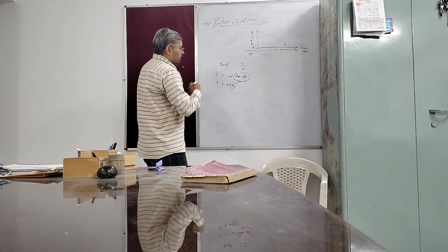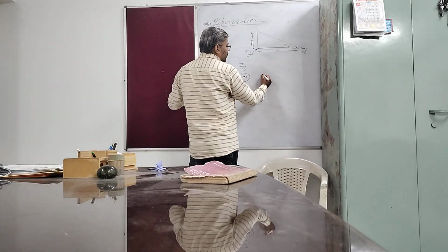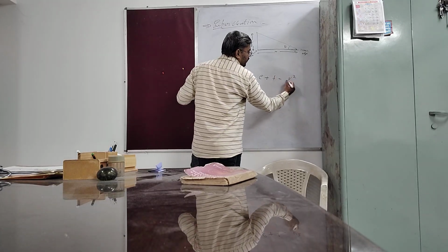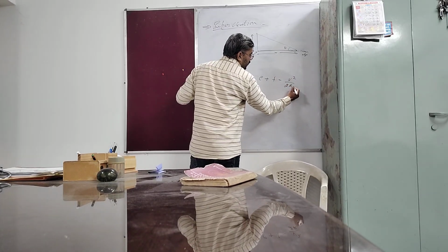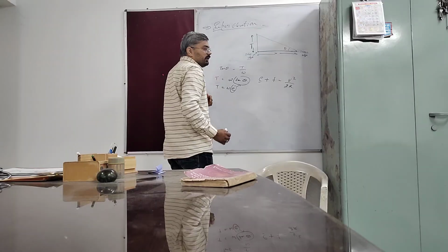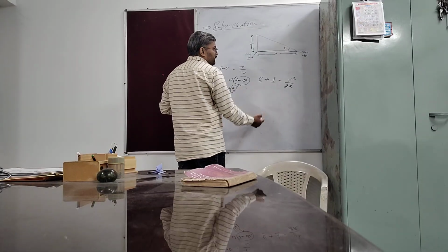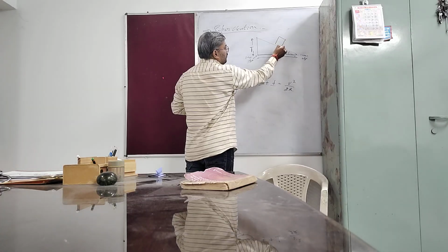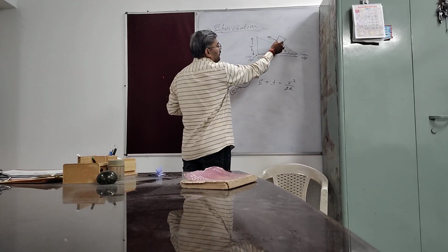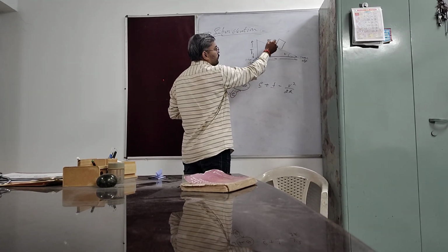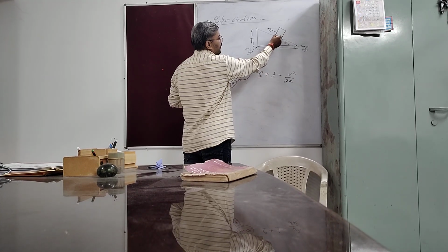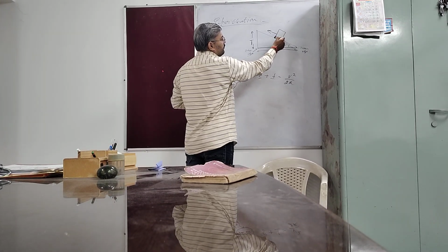Okay, and generally we write the super elevation equation in the form E plus F is equal to V square upon G into R. Here E is the super elevation in percentage, F is the coefficient of lateral friction, which is the resistance friction acting on the wheels of the vehicle when it goes outward due to centrifugal force.